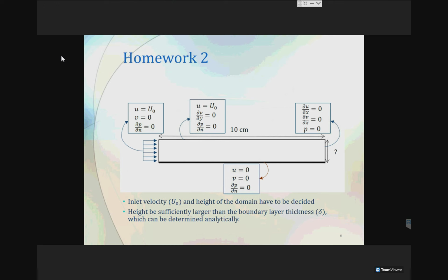So what happens? The mass flow rate that is entering in the x direction reduces. It has to go somewhere, because additional mass is continuously coming in, but not all of that is going out in the x direction, because the plate is slowing down the velocity in the u direction. So where does the additional mass flow rate coming from the back go? It goes upward. So there must be some velocity interchange across this vertical direction, because we specify this condition that u is equal to u naught continuously at each instance of time.